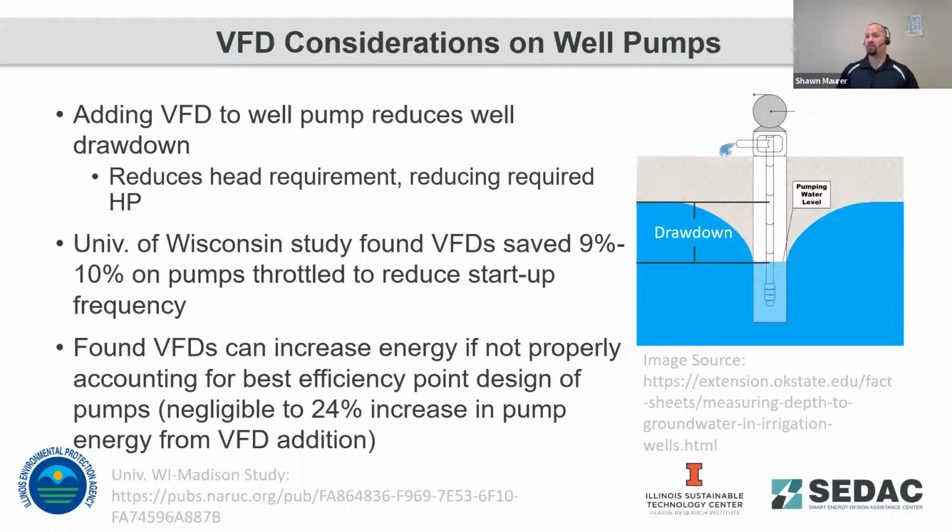So looking at well pumps, for those of you that have groundwater source water, if you're looking at VFD applications, again, that high head pressure versus low head pressure is going to impact a little bit whether a VFD is going to be a cost-effective option for you. But in general, we find that a VFD is effective for these pumps. Sometimes it might require a pump upgrade to optimize that VFD.